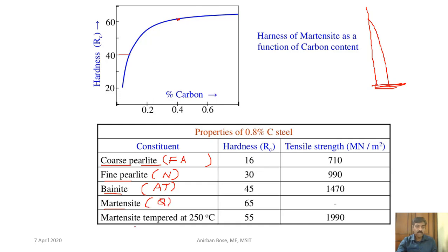Finally, the tempering process. Further, it is heated in the furnace after quenching. So first quenching and then heating in the furnace. Here you can see the hardness changing at different temperatures, and you get some idea that gradually the hardness is decreasing as you go down.